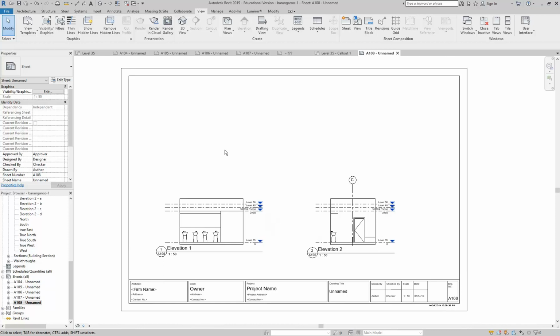It does help the builders on site when you've got a 100-sheet drawing set. It helps them hugely if they can find out when they're looking at a detail which sheet it's being referenced from. So that's why reverse referencing is good. But because of the complexity, a lot of firms just give up and go, let's not worry about it.